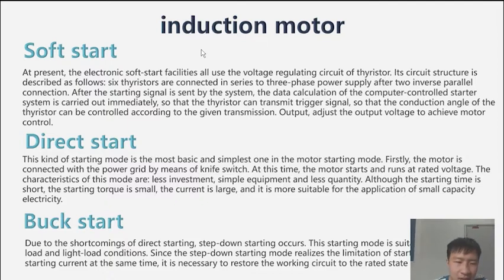The characteristics of this mode are less investment, simple equipment, and less quantity. Although the starting time is short, the starting torque is small and the current is large, so it is more suitable for small capacity motors.